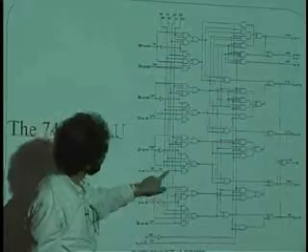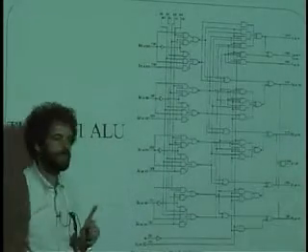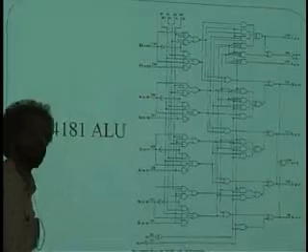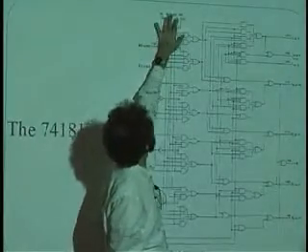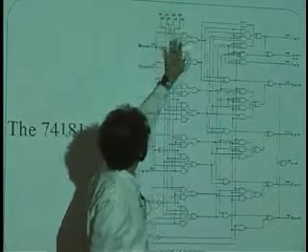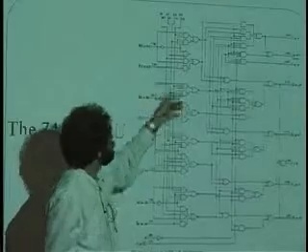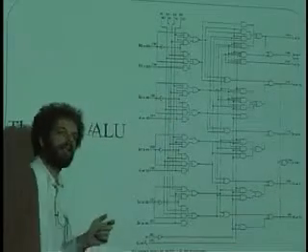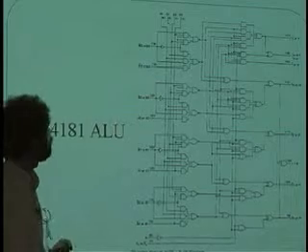Okay? And if you go through the logic here, what fools you a little bit is that this ALU doesn't only add. In fact, this ALU has 4 bits, S0, S1, S2, and S3, that go all the way down here and plug into all these gates, and they allow it to do add, subtract, and or all kinds of fun things.